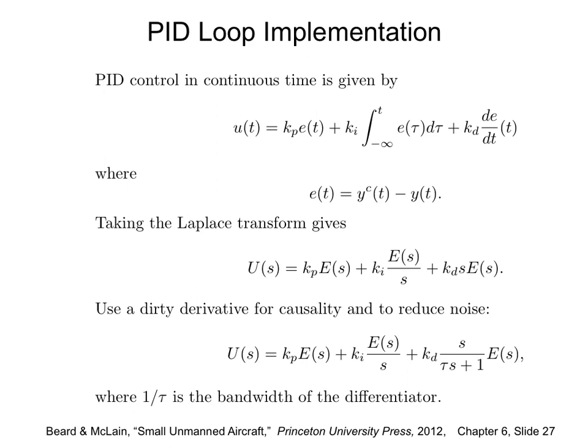If, for example, we are only using a PI controller, then Kd will be 0. If we are only using a PD controller, then Ki will be 0. So basically one general PID loop that you can save as 7 different files: roll loop, course loop, pitch loop, airspeed to pitch, height to pitch. You can write all those 7 different controllers, but I'm just giving you how to actually implement a PID in a real-time system.